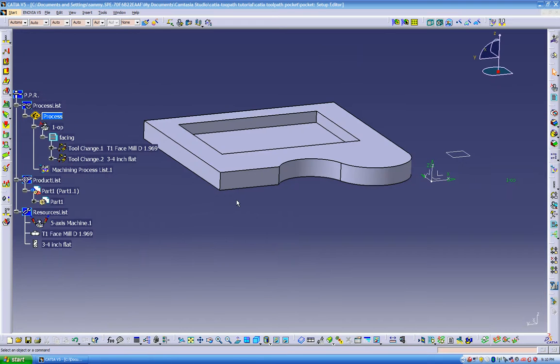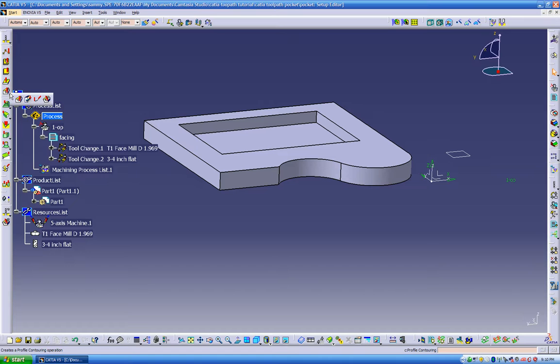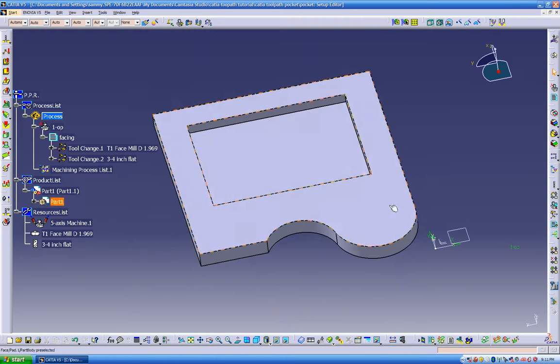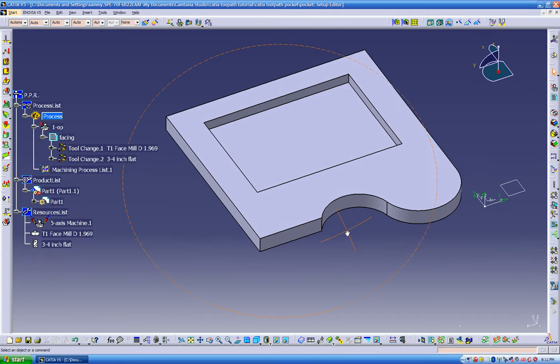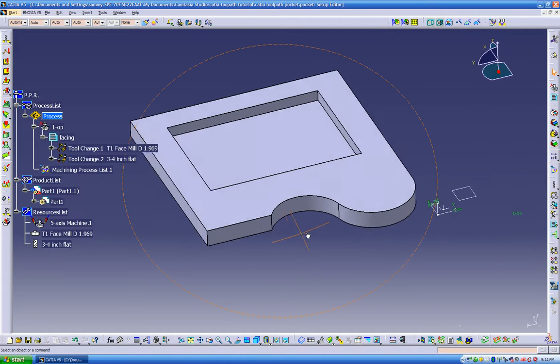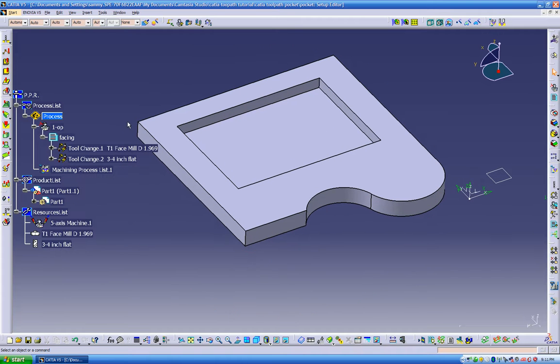Our next option is going to be the profile contouring. We got a couple more options in here, but not for now. So we're gonna give it a try to walk around this part and remove the excess material. What I'm gonna do first, I'm gonna machine this edge, and then I'm gonna machine this edge in here. And assuming they're gonna have two clamps to hold the part over here, then we're gonna stop the program and then swap the clamps and machine the leftovers.